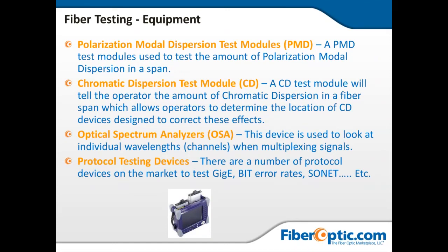Now in the first section, I guess we went a little bit in depth into the dispersion issues associated with high power, long distance outside plant cable. Well, this says that I can test for this thing. Do most installers need to test for all of these dispersions? Most installation contractors will test for the basic OTDR, tracing the circuit, characterization, losses, loss per kilometer distance, total losses.